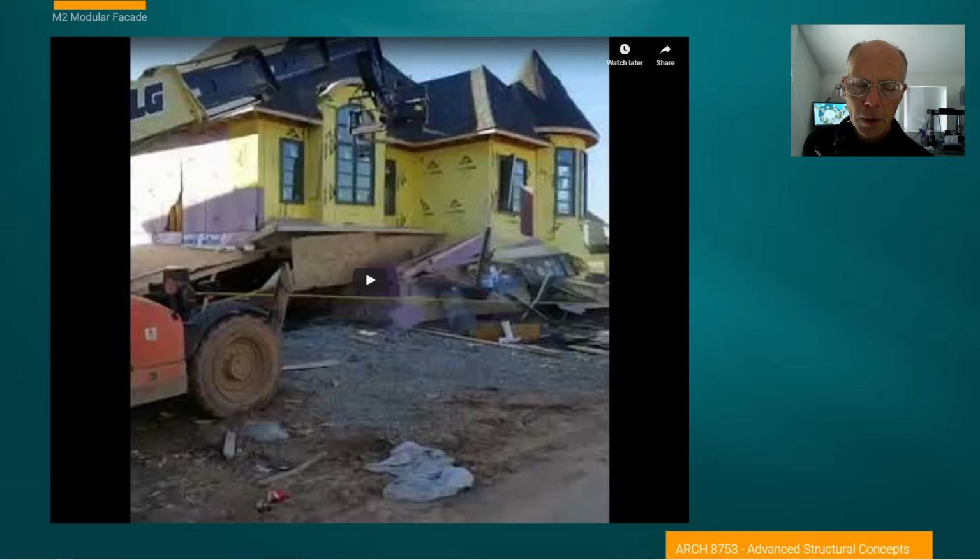For instance, there's all kinds of grades of plywood and oriented strand board that will have the same kind of barrier protections, but without the problem of moisture and other structural issues with it. But you for sure cannot label an exterior sheathing wall as just gypsum board. It must be characterized as a moisture resistant material and a sheathing grade exterior material. Labeling it as gypsum board would just be completely inadequate for that application.